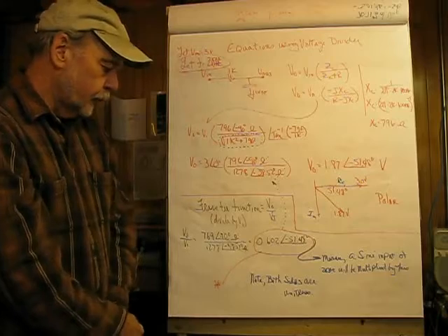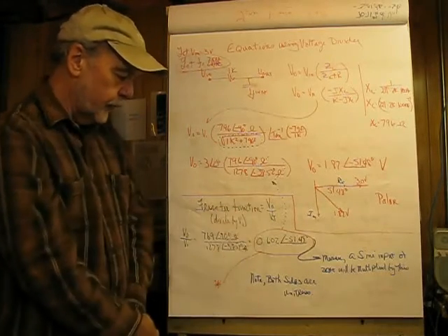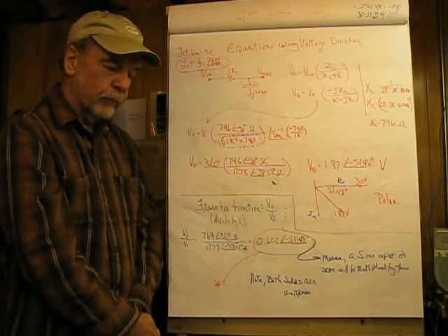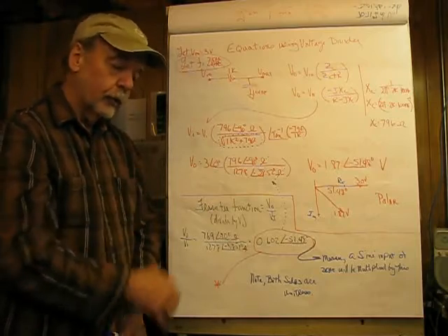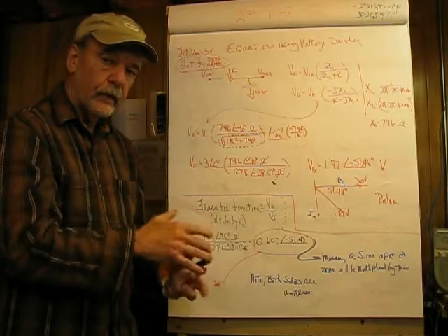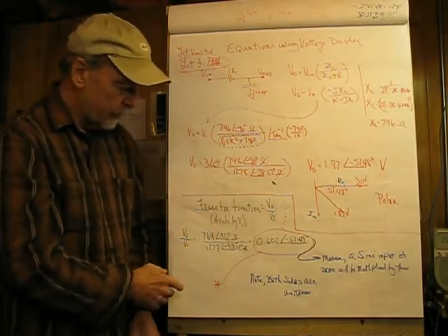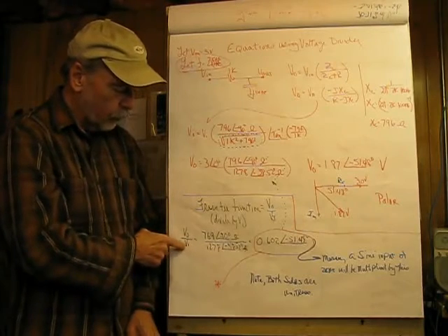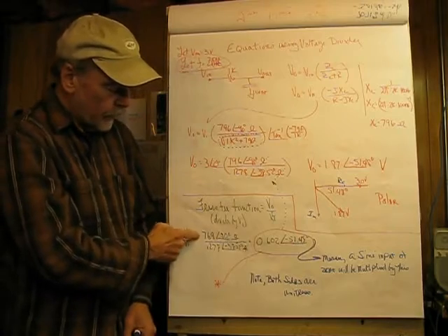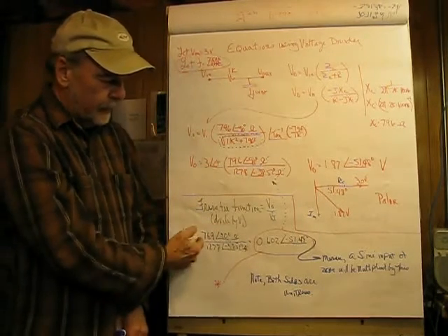So the transfer function is another way of saying this, and this is just a ratio of V out over V in, and you can kind of think of this as a box, and you're going to send a signal into it, you're going to get a signal out of it, and how does that box transform the signal? What does it do to it? So setting this up in notation is just the output voltage divided by the input voltage, and note that this is dimensionless based upon the ratio of what we had before, and then dividing this out is what we get